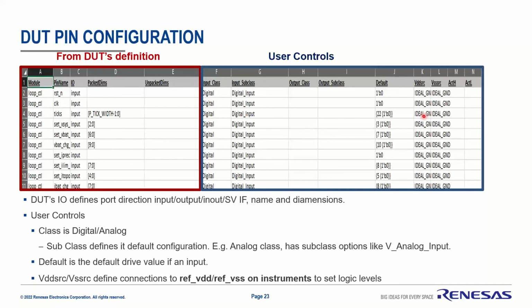And are you able to set different levels of accuracy to adjust performance? So if you've built your DMS test case and then you're running that in AMS, you would probably only convert the block of interest down to schematic and you'd leave the rest as a model.